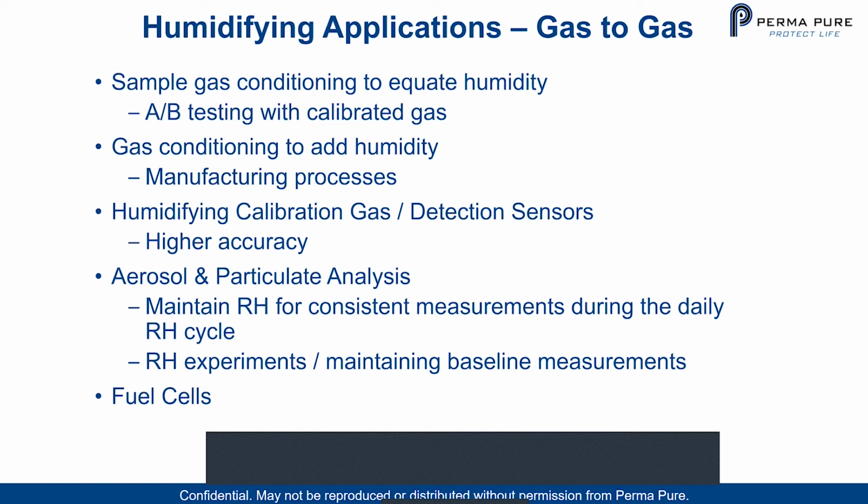For aerosol and particle analysis, we maintain the relative humidity for consistent measurements during the daily relative humidity cycle. It's also being used in extremely dry environments to get a good baseline, because you need to get the relative humidity of particle streams in the 30 to 40% range to get accurate results.